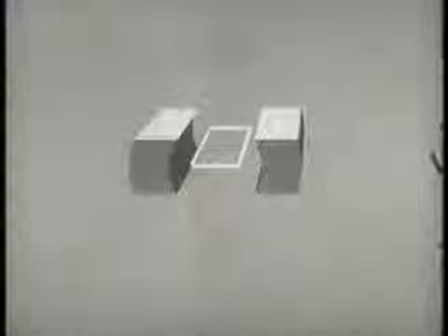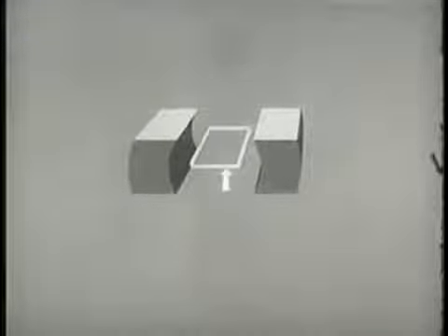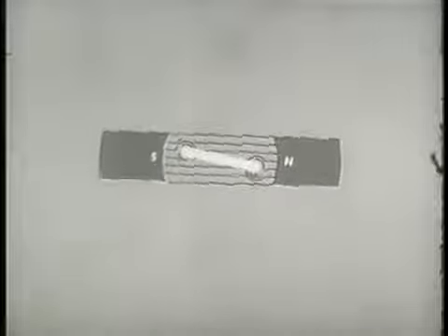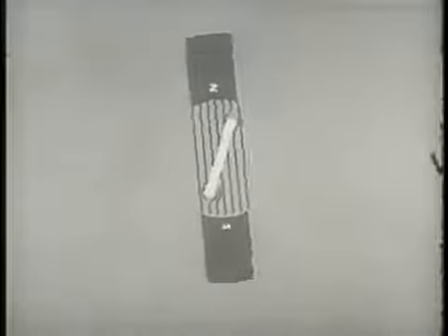We can construct an AC motor by closing the loop ends of the armature, thereby inducing a larger current in the loop and creating stronger magnetic fields around the conductors. This is a simple induction motor. The interaction between the conductor fields due to relative motion and the rotating magnetic field causes the rotor to move, but at a slower pace than the rotating field.